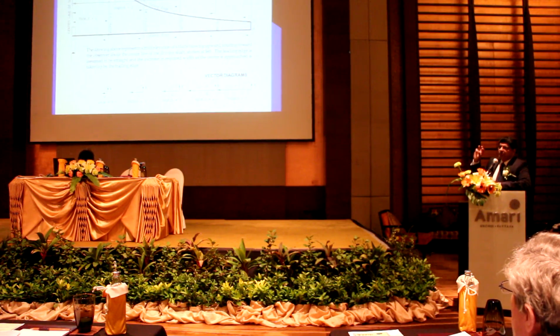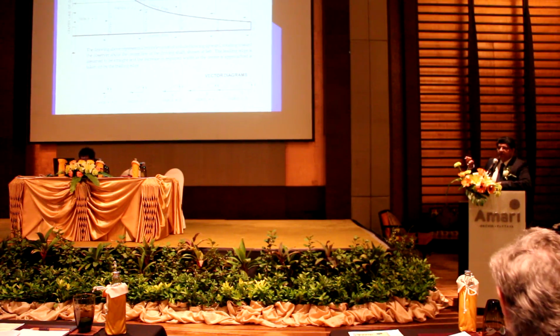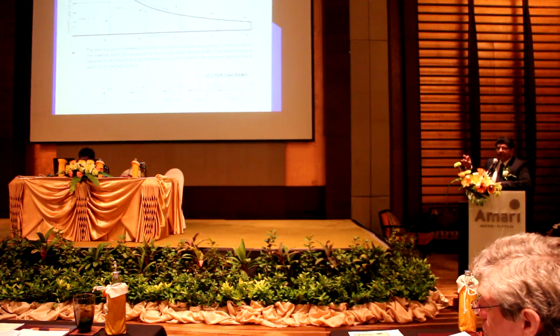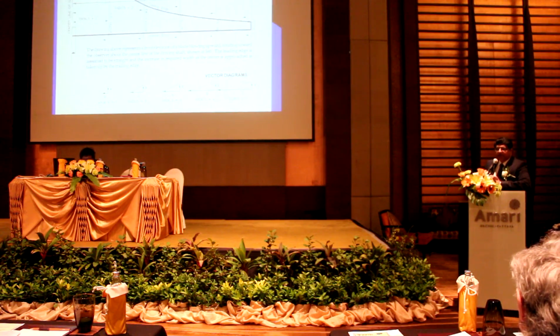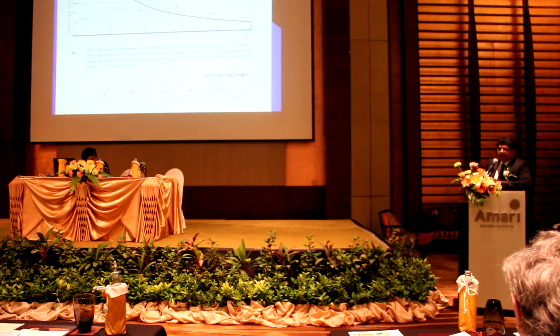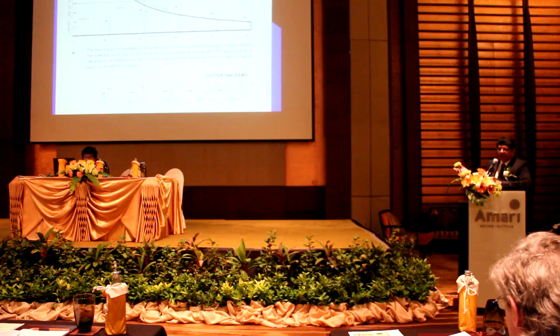Okay? So just because you're able to give higher lift, it doesn't mean you can cut down on the drag associated with it. So in any aerofoil, the lift as well as the drag both are completely interrelated. So the research that has been done is in trying to get the best possible lift to drag ratio, as we call it. So any aerofoil which has a better L/D ratio will give us more useful work.